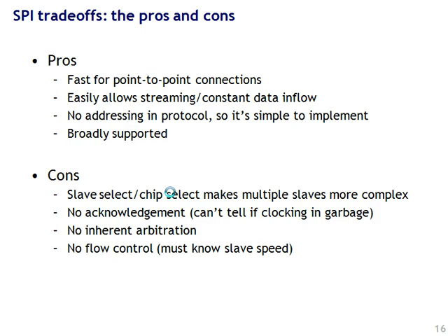You know, if I'm sending data at a gigahertz, it had better take the data at a gigahertz, or else that data is just going to fall on the floor. Buckets of bits all over my clean living room floor. What good is that? So I got no acknowledgement, no error control, no flow control, no arbitration. Stuff had better just work. That's the bottom line. And I better use it within the guaranteed area of operation. That is, if it's only good for a gigahertz and I run it at 2 gigahertz and it stops working properly, I will never know except by seeing the, let's say, unintended consequence of my action.